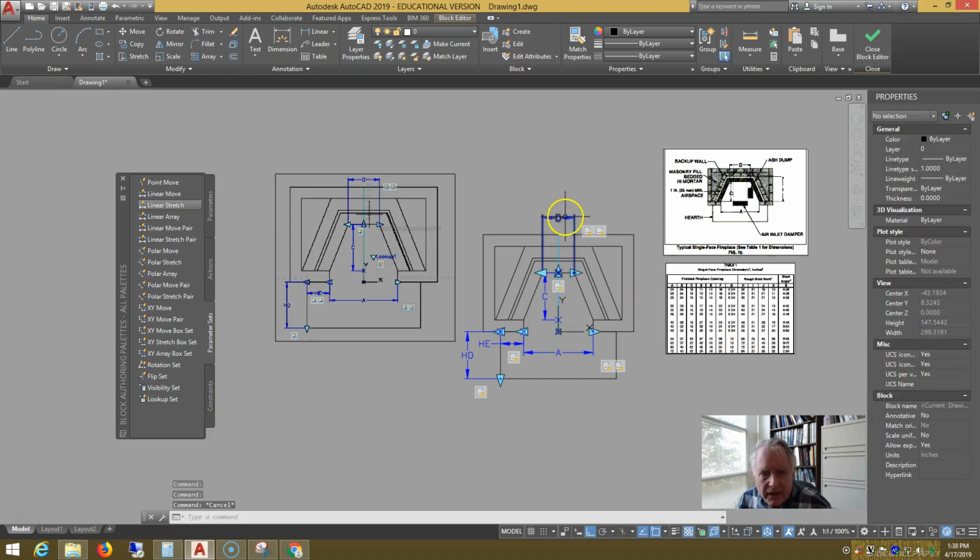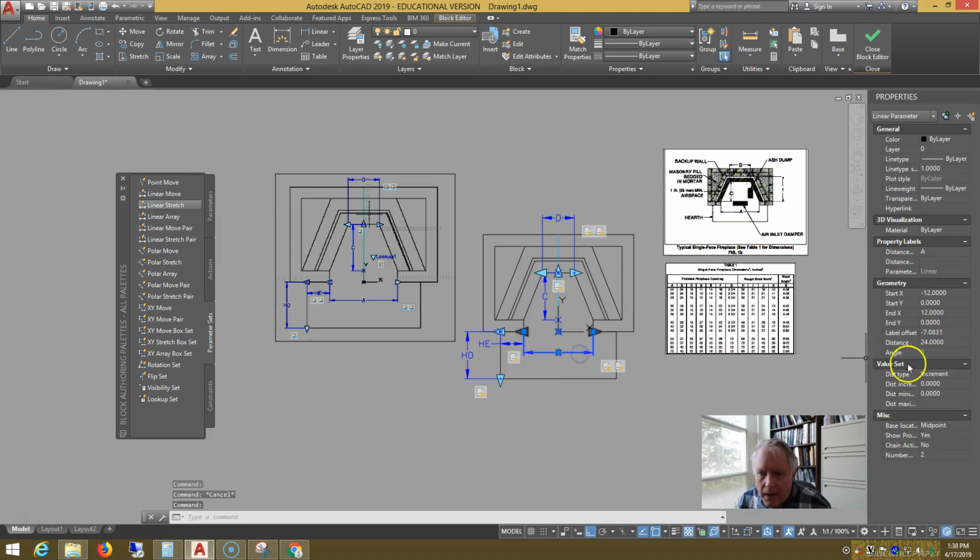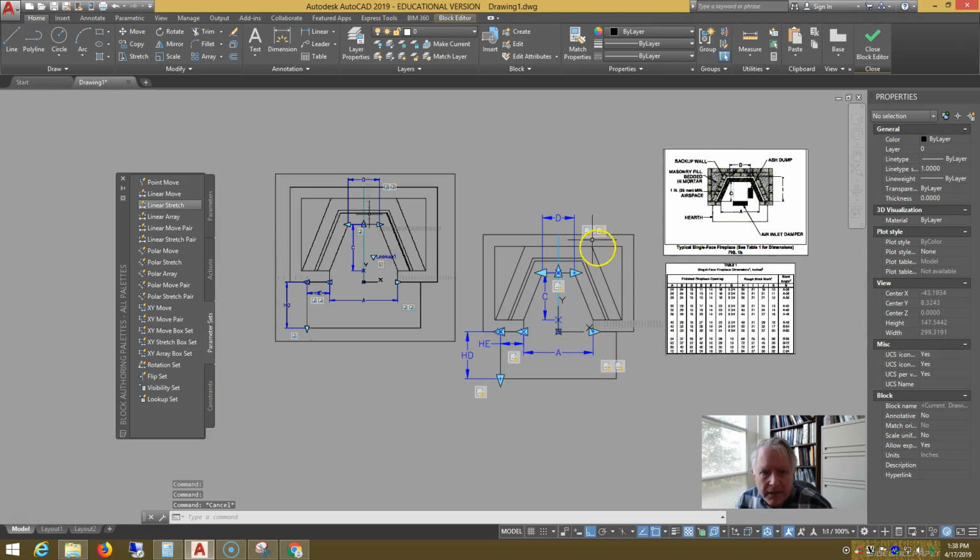So let's just select each one. Let's go A. The distance increment will be probably in the neighborhood of 2. Minimum distance is 24 and the maximum distance is 72. So that's how big this is applicable. This will limit me from accidentally making bigger fireplaces.